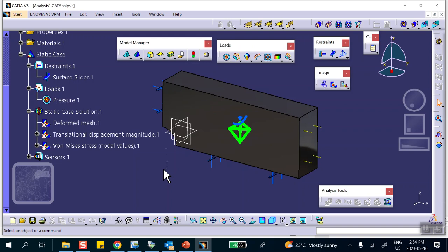The thing that you have to worry about is that you have to make sure the stress place that you're looking for is the critical area. It's not artificially introduced because of bad modeling, like me putting force at the end. And of course, you're dealing with ductile material, for example. If you're talking about yield strength, then you're talking about ductile material in principle.